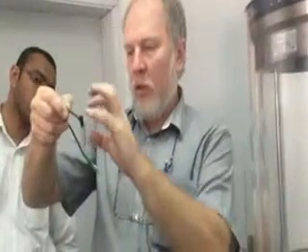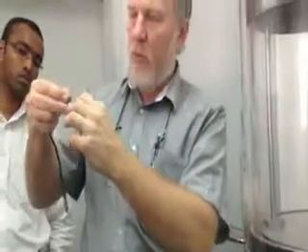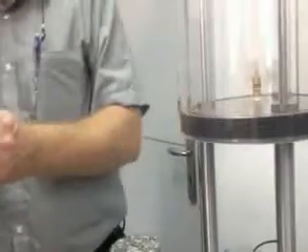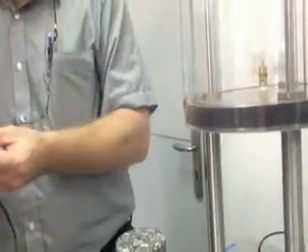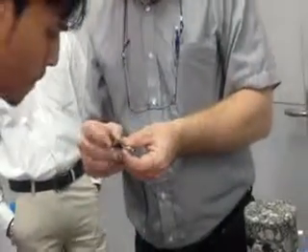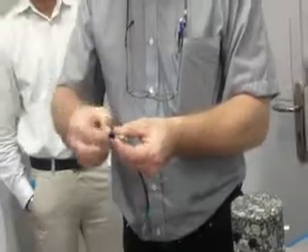So when we come to the software, we need to set up the transducer. When you're running the test, it should be touched on both sides. The transducer will be within its operating range. If it's near one end of the stroke and you run a test, you may lose your signal on the transducer because you've gone out of range. So we'll adjust these when we do a test later. This one here is for locking, and this can adjust the height. When you've got your position, you lock that in and you can't turn.